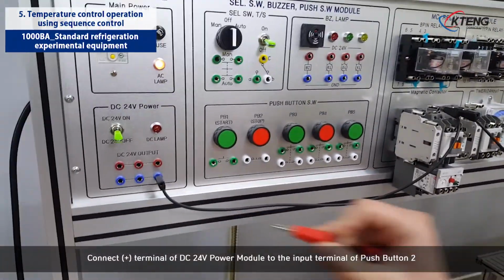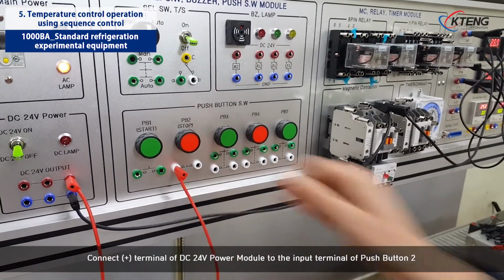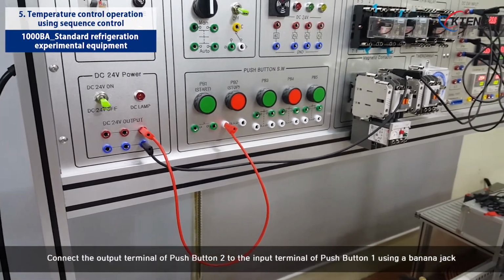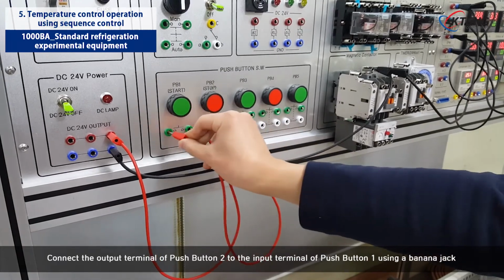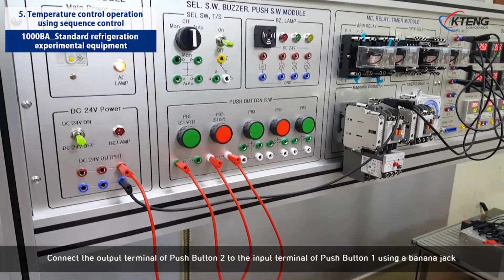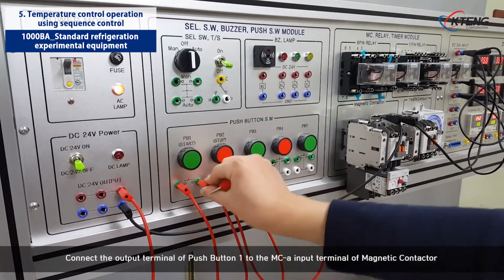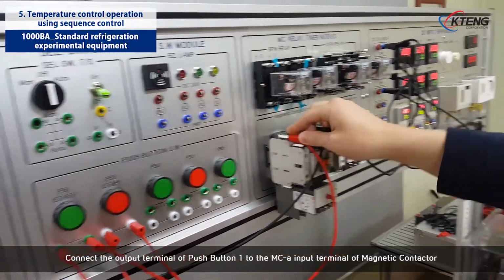Connect positive terminal of DC 24-volt power module to the input terminal of push button 2. Connect the output terminal of push button 2 to the input terminal of push button 1 using a banana jack. Connect the output terminal of push button 1 to the MCA input terminal of magnetic contactor.